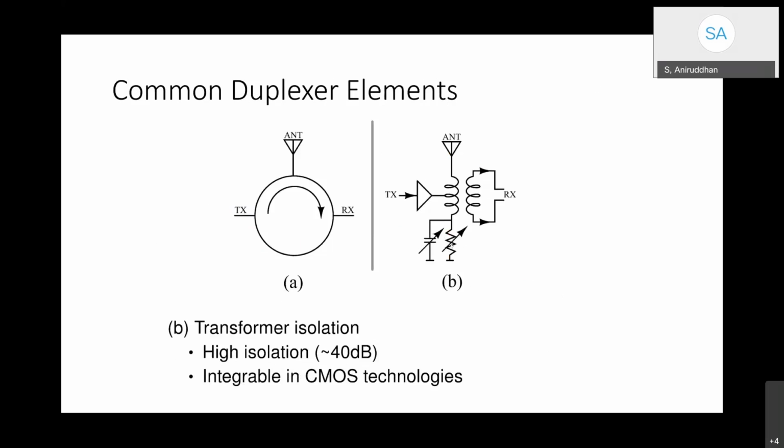But that tuning matches the antenna impedance to get cancellation. That does not necessarily always give you wideband operation. Number two, the tap of this antenna port, for example, cannot be varied. So the transformer is what it is. The primary, secondary, and secondary inductances and the mutual inductances are fixed.